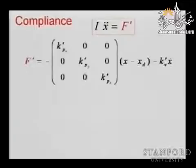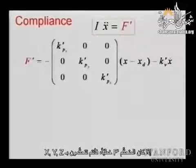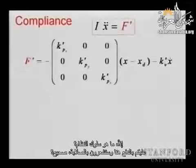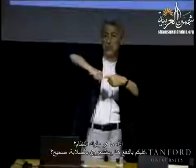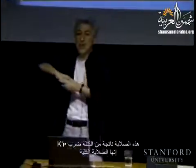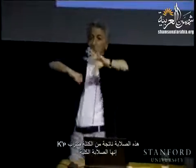So if we think about the controller f prime to be just a proportional controller, you're controlling x, y, and z, and you have a kp prime, kp y prime, and kp z prime. So what is the behavior? You push here, and you're going to feel some stiffness. And this stiffness is going to come from your mass times kp prime. It's the overall stiffness.